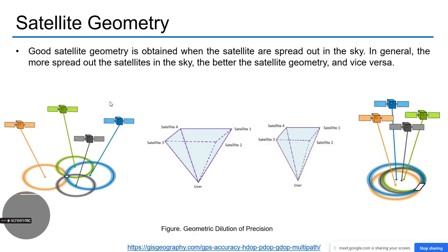So when we consider GDOP values, it looks something like this. If your satellites are distributed away from each other, then when you do the intersection of all four, you will get one location. But if they are nearby, as you can see on this side, where all satellites are close together, then if you plot these circles for all four, with the uncertainty range, instead of giving a point it will give us an area with some length and width.